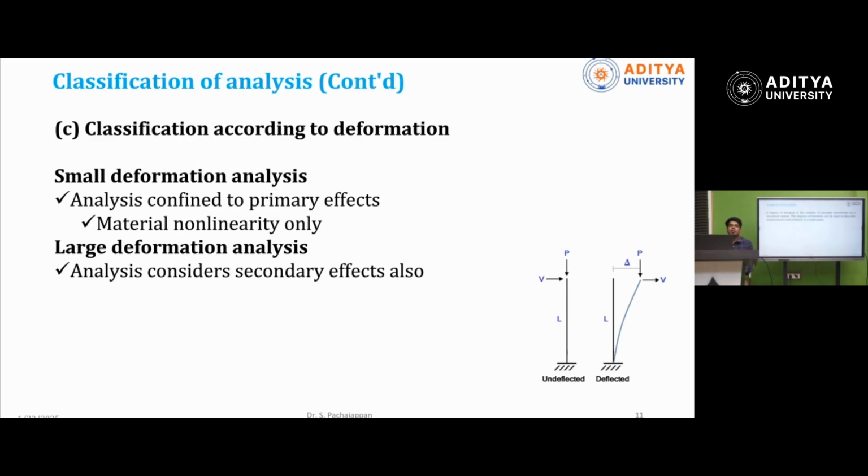So this terminology I have already explained, degree of freedom, but we'll discuss it in more detail here. Degree of freedom in structural dynamics or kinematic indeterminacy in structural analysis, both are the same. That means the number of independent coordinates required to specify the motion of the system. For example, in structural analysis, if you consider a fixed beam, it cannot move in any direction. Both support conditions are fixed. So the number of displacement coordinates for the fixed beam is 0.